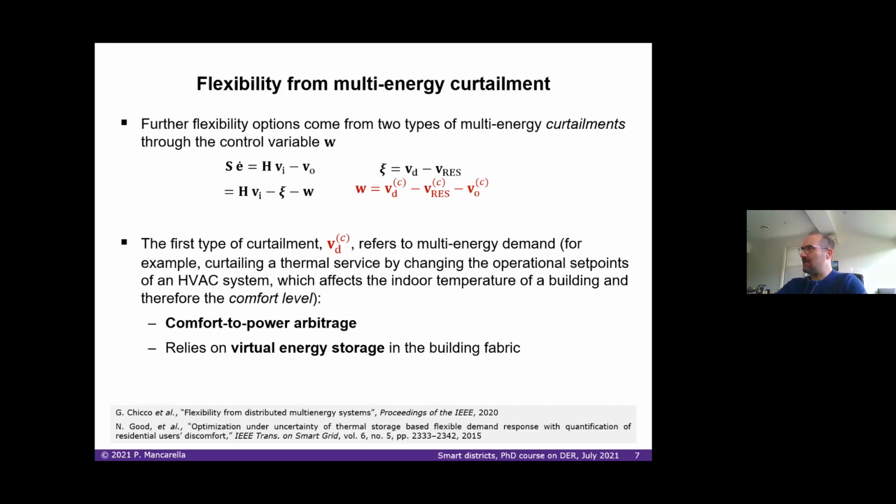The other way I look at this is the fact that you can only do this because there is a certain virtual energy storage level intrinsic in the building fabric that basically enables the thermal inertia of the building to slow down the changes in the temperature.